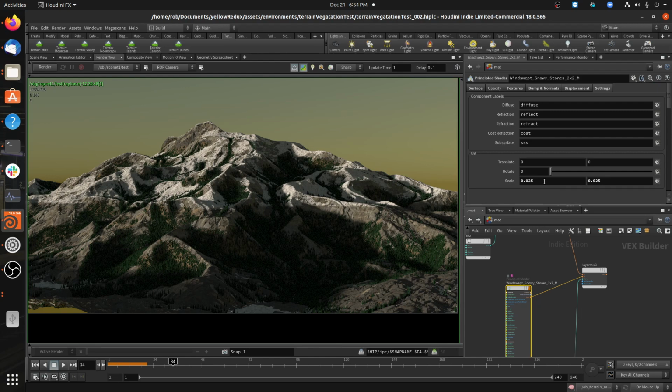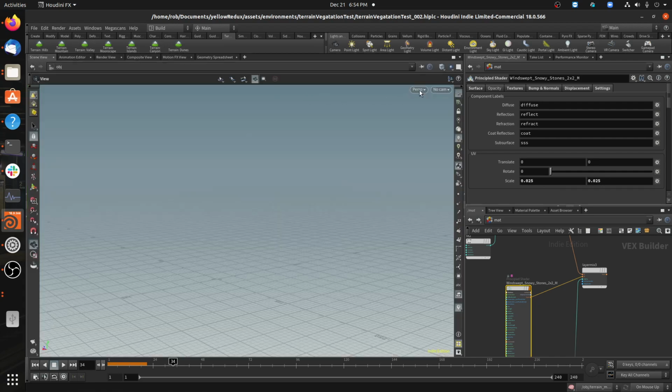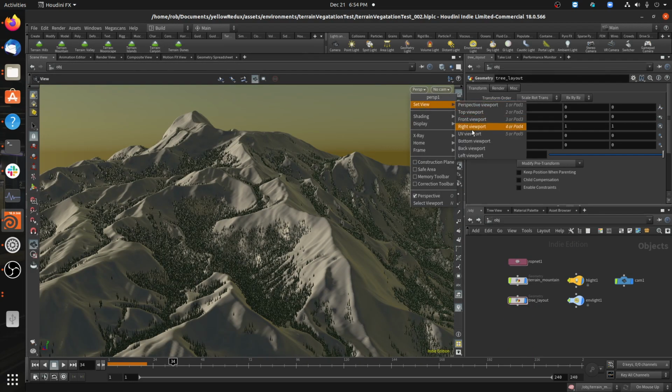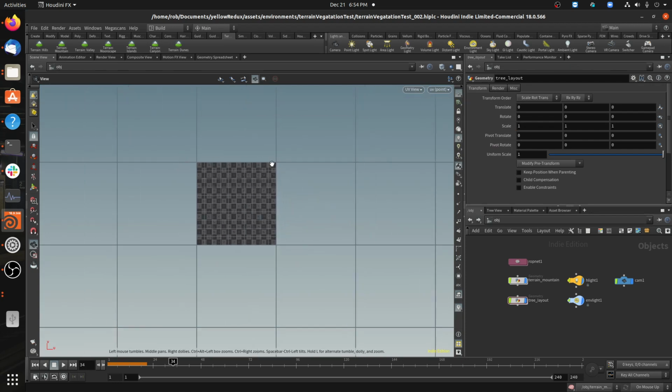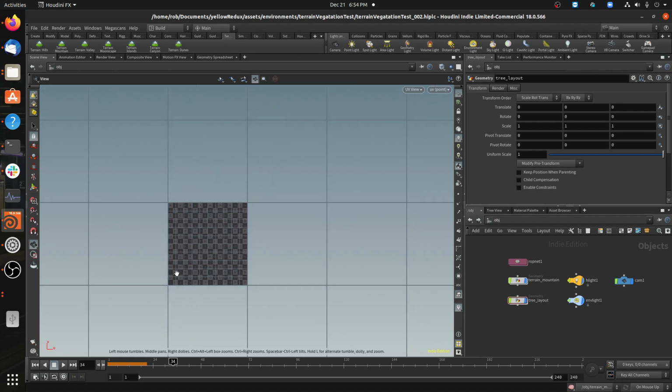I would think that scaling the UVs, if I took a UV grid and this was a square and I multiplied it, so if I went here to the UV viewport, I would expect that if the UV occupied this and I gave it a value of 4, or 2 even, this would scale up to encompass this, and that texture map would be on each one of these tiles, which would then make it repeat more. That's how I would expect that to work. But that's not how it works.